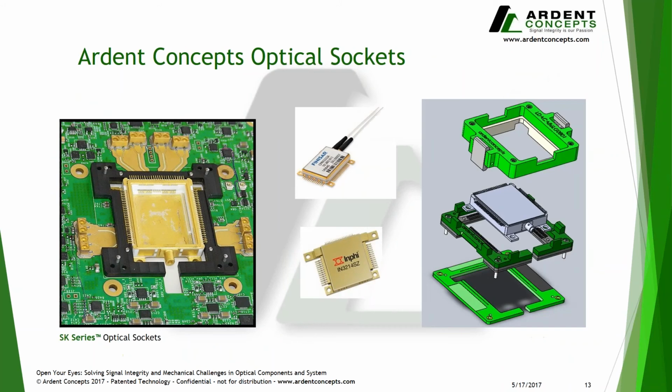So here's a quick example of what Ardent is doing to create some socketing solutions for similar butterfly style, if you will, leaded packages related to those optical modulators and coherent receivers. On the left, we have a photo of our socket, and you can see that there's an unfinished open-top package sitting on top of our socket guide plate, and then on top of the PCB. On the right, we have an exploded view of a model, which I can walk through briefly. On the very bottom of the right image is the PCB. Just above that, we have the socket guide plate. And then above that, we have the clip-on lever lid that holds the whole assembly together.